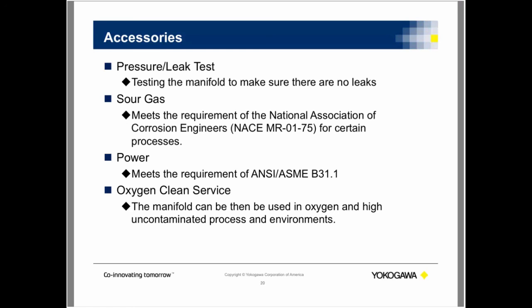There's generally two different tests that can be done. These are just two popular ones. There are other tests you can do, but these are the hydrostatic test and the nitrogen test, and they're usually 1.5 maximum. So you test them to 1.5 times the maximum working pressure of either the transmitter or the manifold. Most people go by the transmitter.